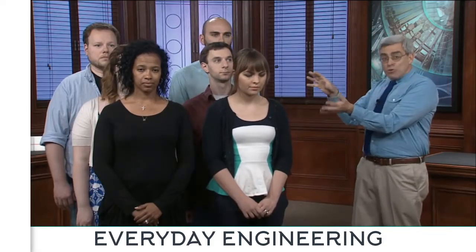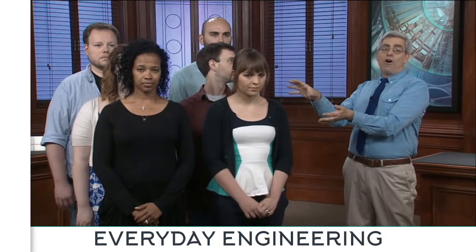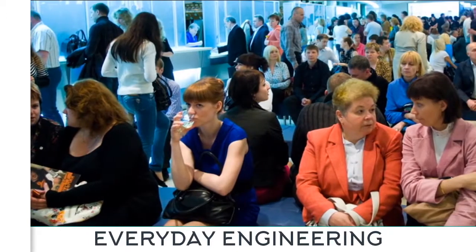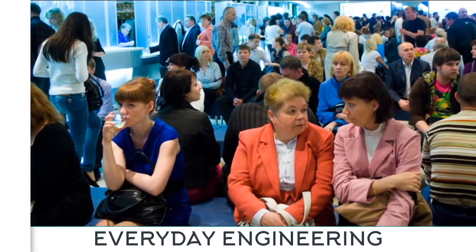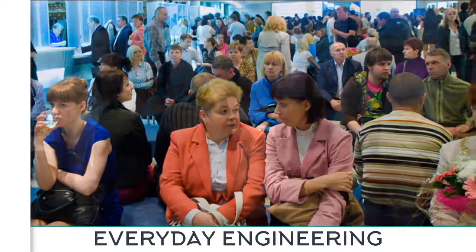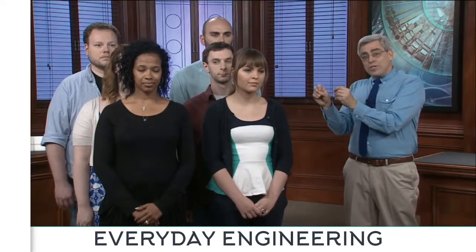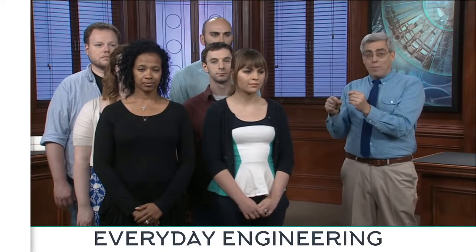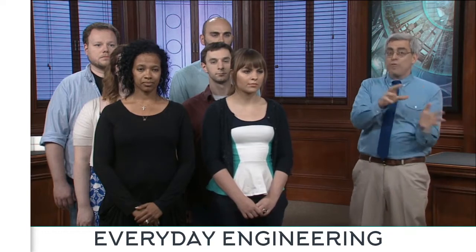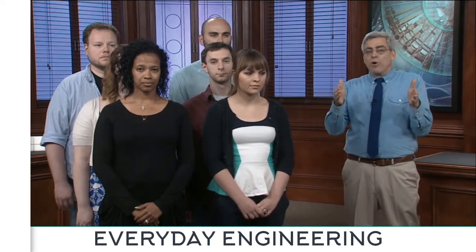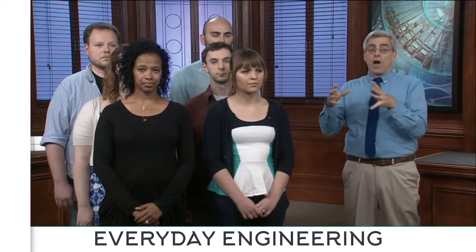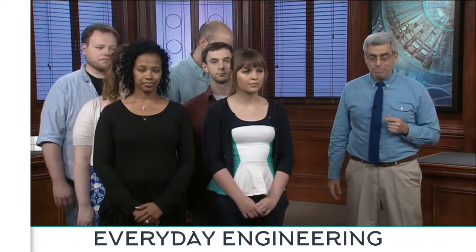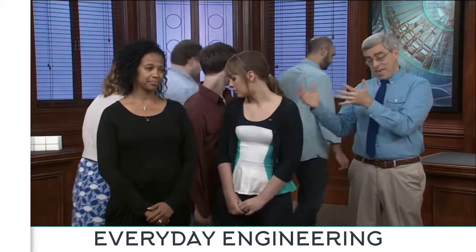Now, by the way, people do stand this close together quite often in the corridors of lobbies, public buildings, and theaters and auditoriums. And not surprisingly, the code-specified loading for public corridors and lobbies is not 40 pounds per square foot, but 100 pounds per square foot, which actually gives us a nice margin of safety beyond the 85 pound per square foot loading we just derived from this simple experiment. Thank you, live load.